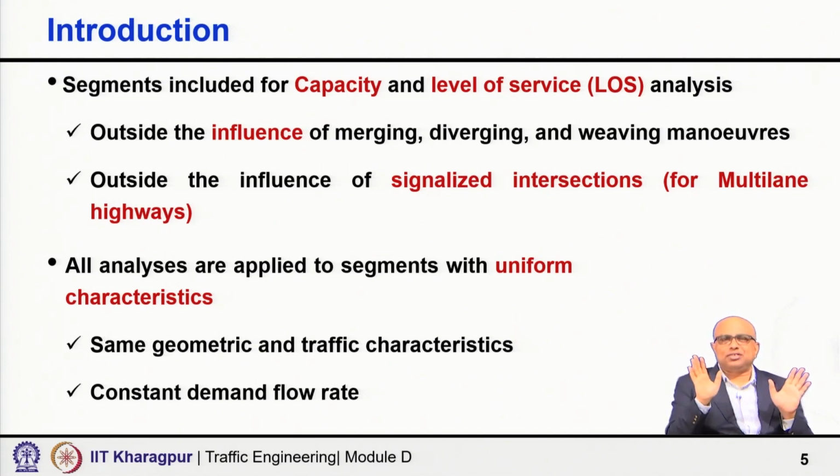All analyses are applied to segments of freeways and multi-lane highways which have uniform characteristics. That means, when we say we are analyzing a segment, the segment has the same geometric and traffic characteristics within it, and also a constant demand flow rate. Those are some basic assumptions.